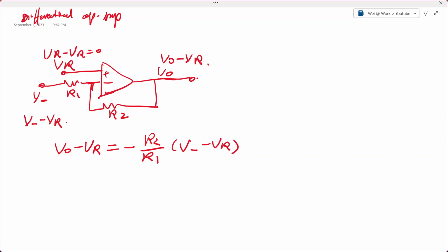Let's erase what we wrote here because we already have the transfer function now. Now, VR is a virtual ground, a voltage you can set to basically any value you want. What's the easiest way to set this VR value? The quickest way is with two resistors, called a resistor divider.